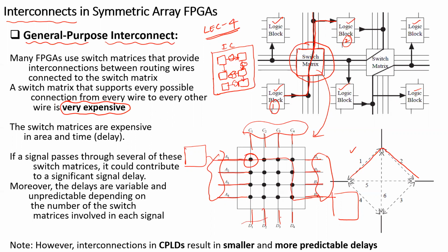So establishing the switch matrix network is very complex, and it is very expensive in terms of cost as well, because we have to provide everything. Because of the huge interconnects, almost all the blocks are connected with the switch matrix, meaning each and every line will be associated with a switch matrix.